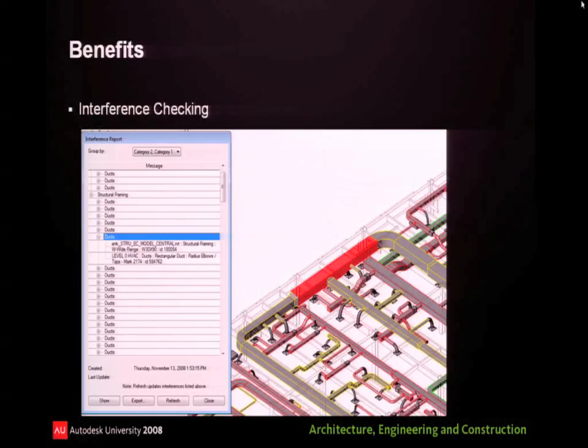Revit has a built-in interference checker. Navisworks is something else we use. Navisworks has more capabilities; however, it's a dead copy. Revit is about as live as you can get. As soon as someone saves it up to the central file, you can interference check very quickly against that information, instead of pushing it out to an external Navisworks file.